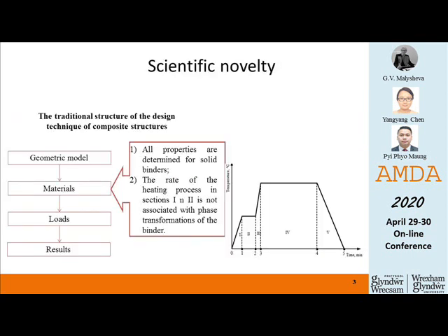It is known that the quality of the parts made of composites based on thermosetting binders is finally formed during the technological operation curing. A typical two-stage technological process of curing the binder consists of 5 sections. On the first and third, there is an increase in temperature. On the second and fourth, aging, and on the fifth section, cooling. The time and temperature in the second section are determined as a rule experimentally for each particular product. It corresponds to gelation time and temperature.